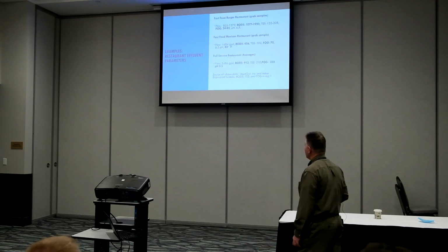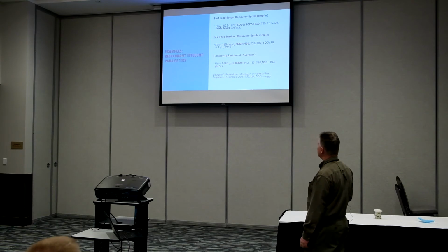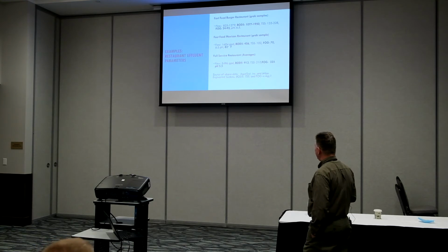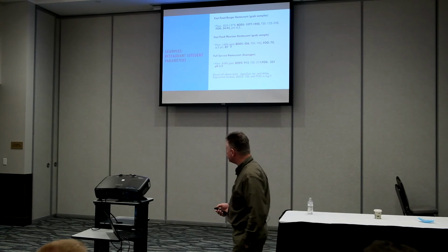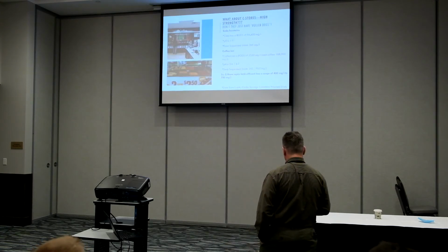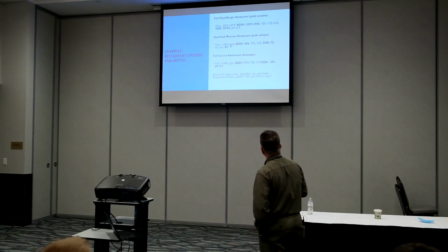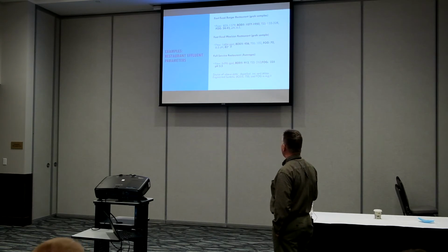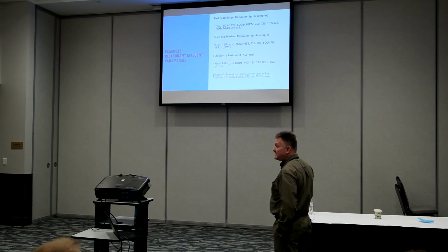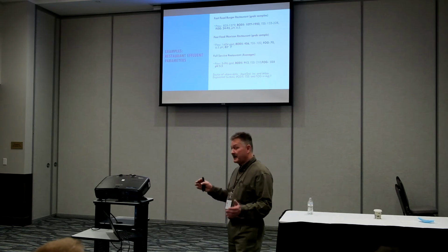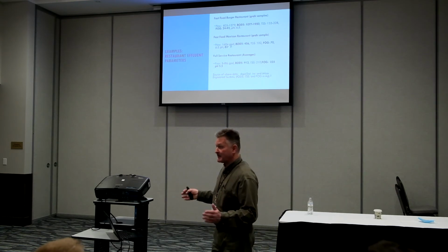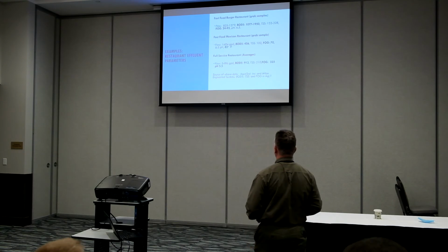So here's some more examples of waste strength. This is some data that I collected when I was working underneath Aquatest on some of their treatment systems. So, here we go. If we look at a fast food burger restaurant, those BOD ranges can really change. With multiple samples, we have ranges from 1,000 to almost 2,000. That's what I'm getting at. We have to get multiple sample points. We can't just sample one time and base our design on that.